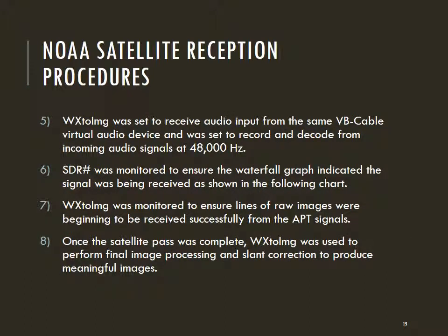The next step was to wait for the next overhead pass of the NOAA Weather Satellite 18. Once this started, since the audio signal is being fed to the Weather to Image software, we had to visually monitor the waterfall graph to see the initial signals being received by SDR Sharp. Subsequently, the Weather to Image software was monitored to see if lines of the image were beginning to be decoded from the audio tones.